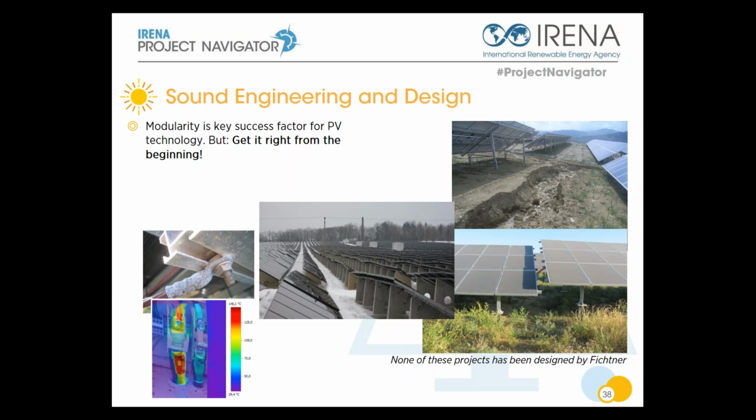Then you see module misalignments or erosion on the ground, and misalignments causing power generation losses as at the lower right side, which also cause certain stress on the bypass diodes and on other elements in the plant design.